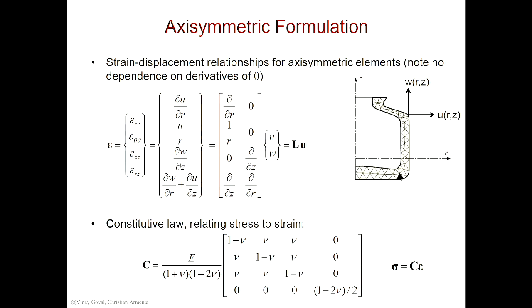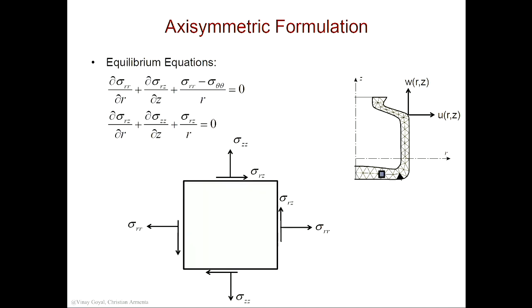Okay? Abaqus also allows you to visualize a 3D field, so you can actually mesh that, and then you can revolve it 360 to see if that is correct. Okay? Anyway, do you guys get that? So r is x. My opinion is that you want to put a node at x equals 0 and y equals 0, and then at y equals 1. That way you know where the axis is, and everything has to be from there. That's what's going to be revolving. Abaqus will do the revolution for you. You don't have to do anything else.